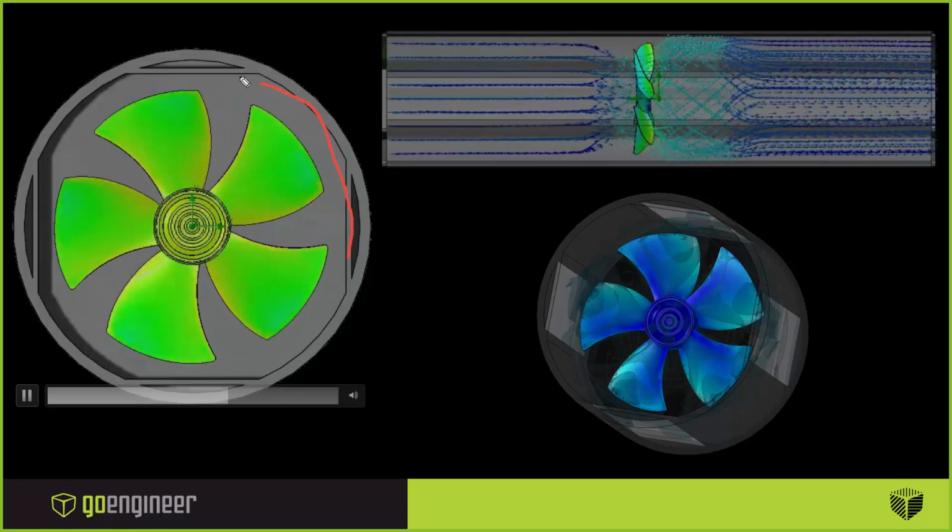If I had accidentally made that rotation region big enough to include the ribs, they would have rotated also, even if I applied a stator condition on them. So, to summarize that answer, I highly recommend your rotation region only enclose the rotor, just for human error, okay? Just to prevent any errors.